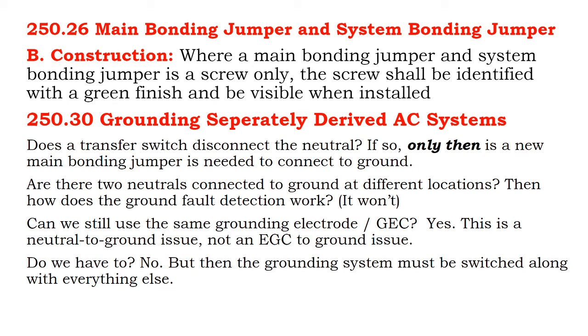I would recommend going ahead and getting 3-pole switches, because sometimes, like on one-way battery inverters, like battery backup UPS systems that don't backfeed the grid, they can't operate tied into the utility neutral. So getting a 3-pole disconnect switch for your hot, your other hot, and your neutral, even if you don't use the pole that's intended for neutral, you'll have it there. You can get 2-pole disconnect switches, you can get 3-pole disconnect switches.